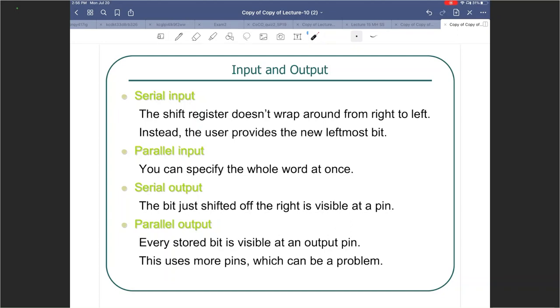So you have to wait for everything to get clocked through all the flip-flops to be able to read serially. Of course, we are doing bit by bit communication, so it will take you much longer. However, the advantage of serial communication is the real estate is much smaller, right? You sacrifice time for real estate in that case. Parallel out takes you more space but happens in parallel, so time wise it is much faster.